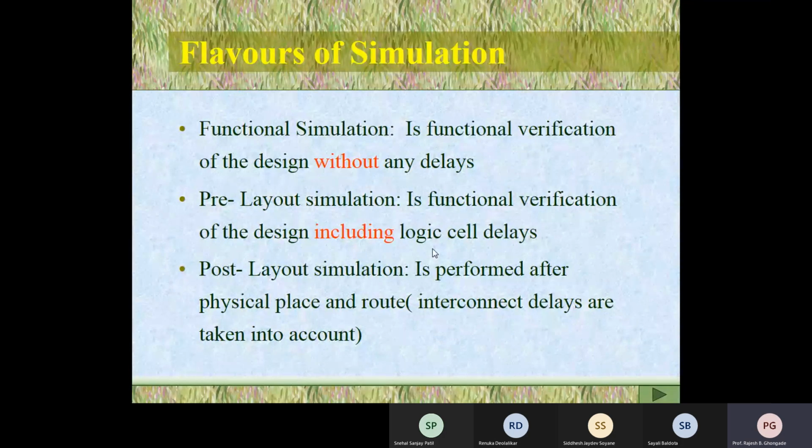Then you have something called pre-layout simulation, which is a functional verification of the design, including logic cell delays. So this is basically another level of simulation where you include the delays also. This is more perfect, approximating the real hardware.